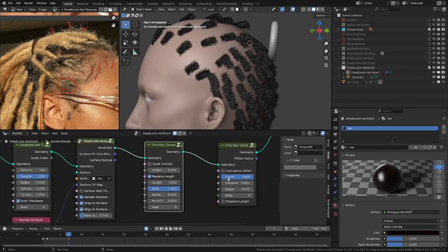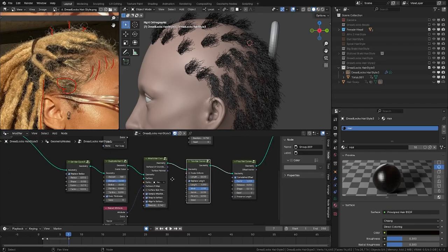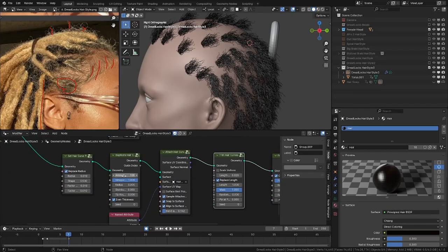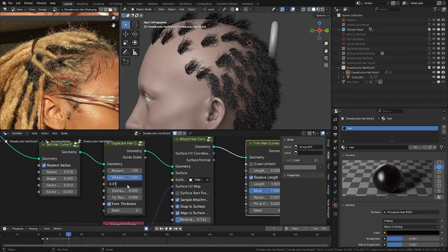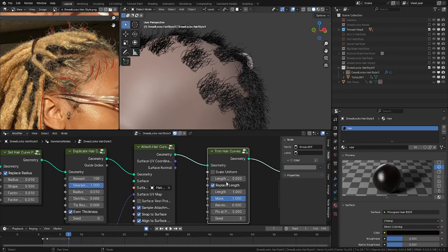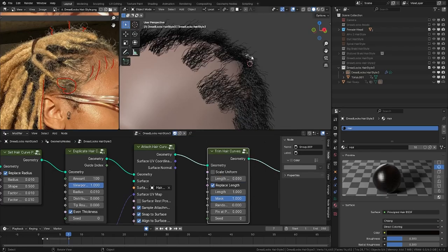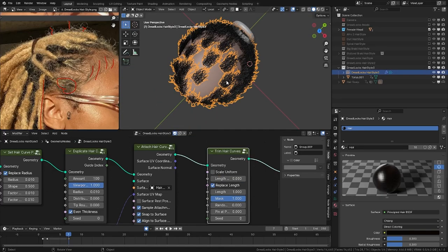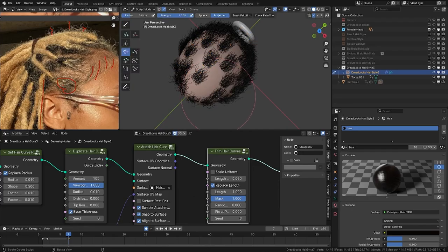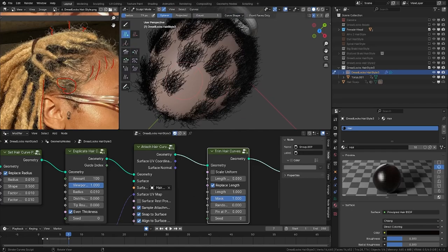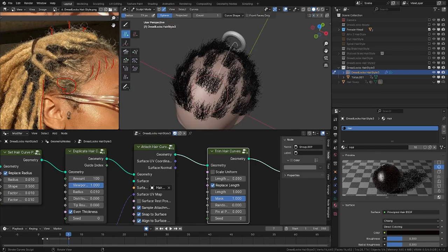The next thing that I'll do, I need to enable cumulative offset, and on duplicate here, I'll increase the radius a little bit, 0.1. Let's increase the trim amount to 0.03. Yes, this is enough. Next thing, remember, we can add here. Let's fill this gap. Can use add and then interpolate everything. Shape, I want to add, disable X mirror here.